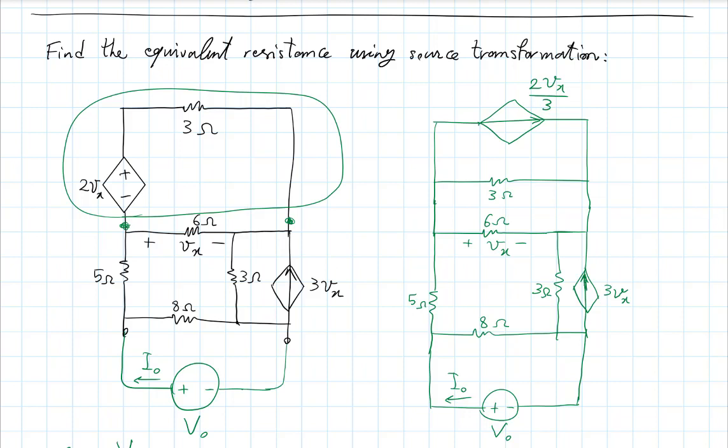So my goal is basically now to convert this to a Thevenin. So how do I deal with Vx now? If I start converting things, all of a sudden, so let's try that. So let's convert that. So 3 and 6 in parallel are 2 ohms, right?